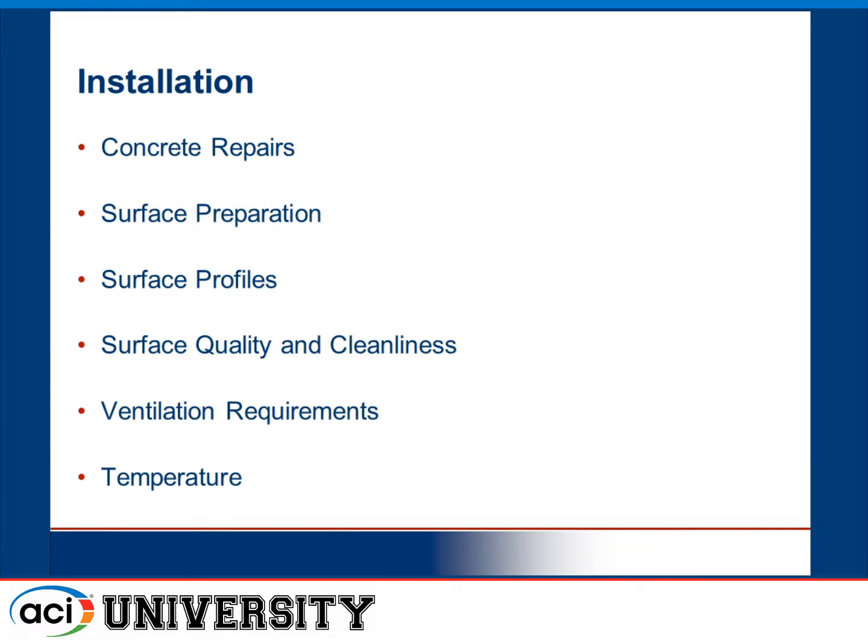Installation of these protective systems requires an understanding of how they're going to operate within the structure after it's been decided which type of system is going to be used. It's important to understand that the concrete repairs need to be completed, many times fully cured. Some manufacturers will give you time frames that may be less than the full 28 days that we typically expect for concrete to cure. So you need to follow the manufacturer's recommendations in cases like that. But we expect all concrete repairs to be completed.